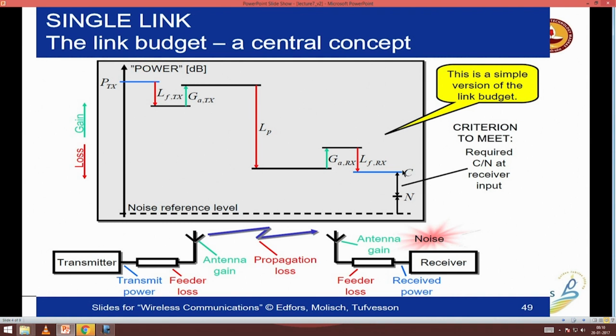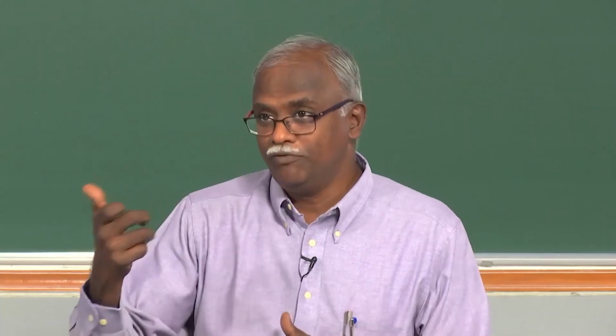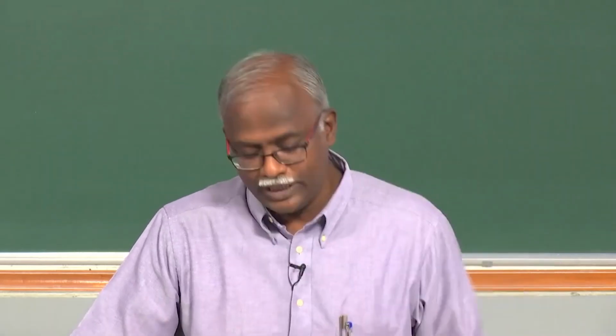Okay. Now, what else can happen on the receive side? You may have an antenna gain. Antenna gain will boost the received signal strength, so that gives you a plus. There may be antenna connector losses, so you must account for that. That will cause an additional drop. Most of the time they cancel each other, and therefore you don't see much of a gain. However, as I told you yesterday, you may be holding the phone in a way that causes additional loss that you have to account for.